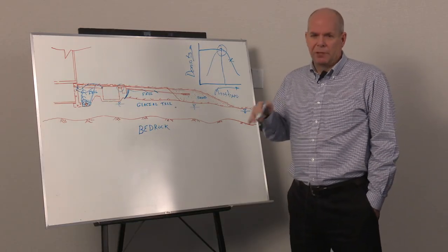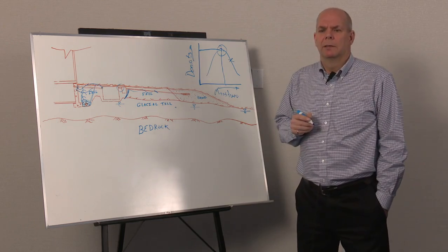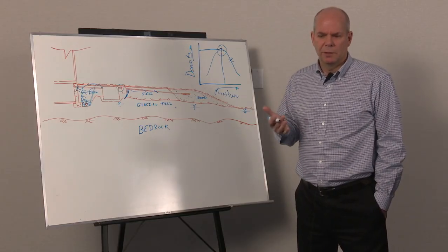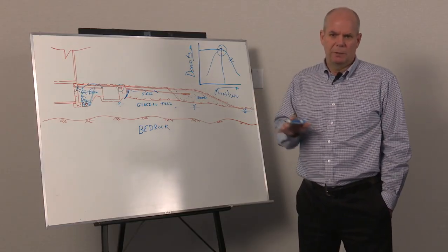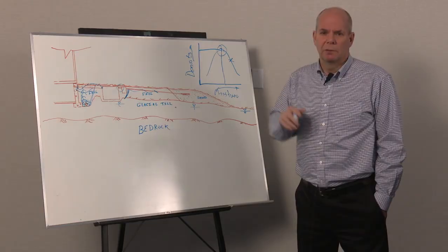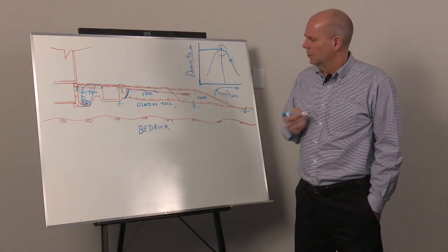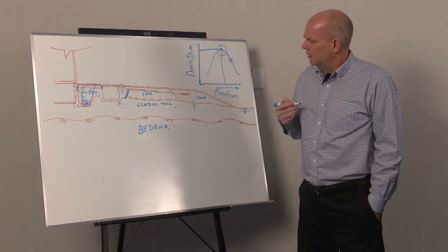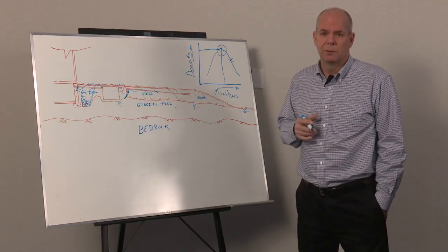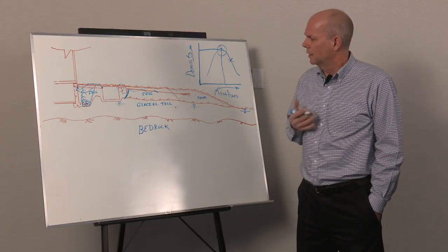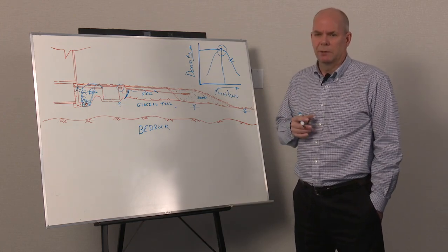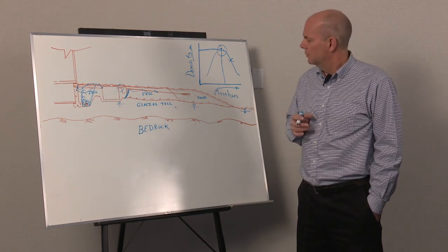And if you have a shallow pipe buried within that material, it will feel those movements as well, and you can break the pipe or deform it. It'll take the shape of whatever the rut and whatever the wave is doing that you're trucking on. So you should plan your hauling and your work so that you're avoiding crossing your pipes, for sure, so you don't develop that condition. But that's very common if you're hauling a lot of materials onto site, on the clays especially.